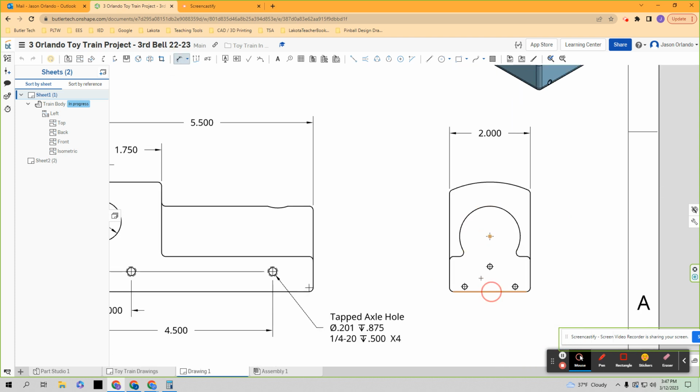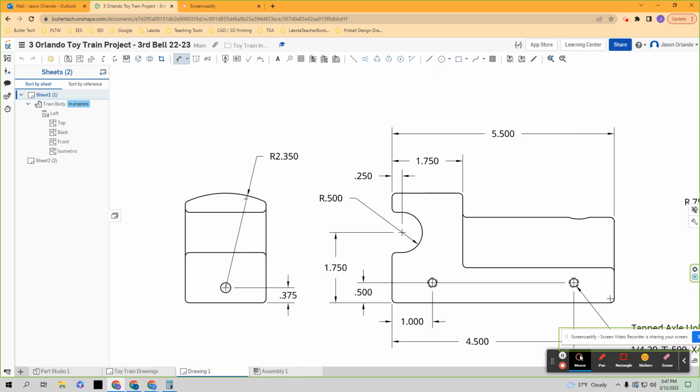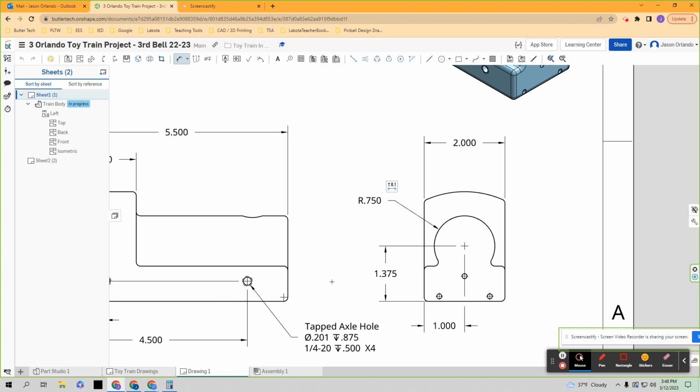So if I locate the center mark, now locating it would be with a vertical distance and a horizontal distance. So now I know where the center is, and then I size that feature. Okay, then that would determine exactly where this is. So I have located that center mark and sized the round feature. The arc on top, that one I've already done over here. Okay, so I don't need to do it again. It's the same thing. The only thing I need here, let's see, oh, one more thing from the front view